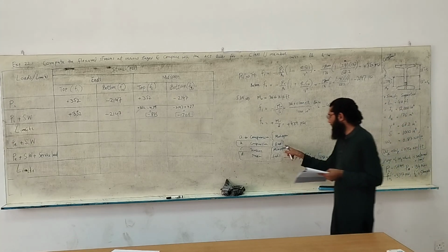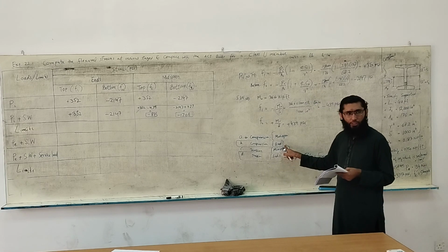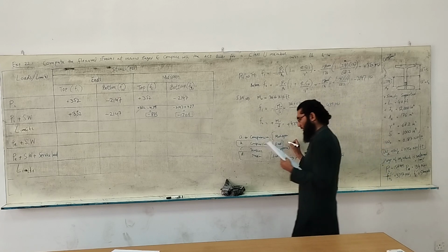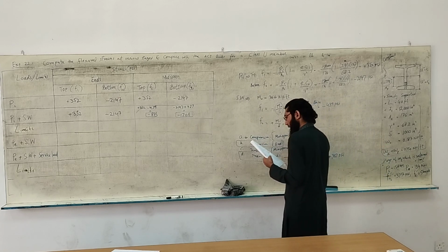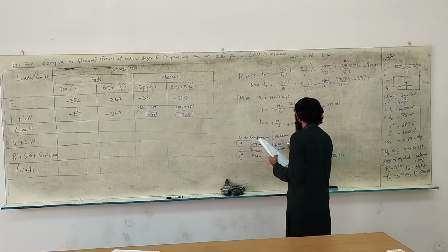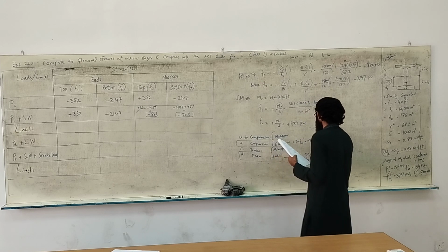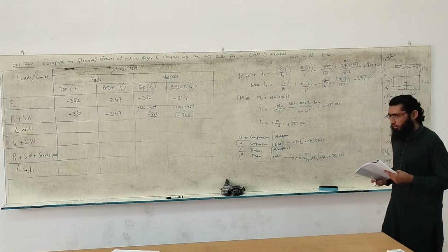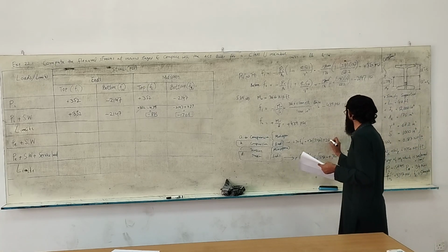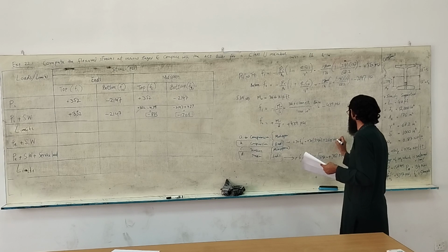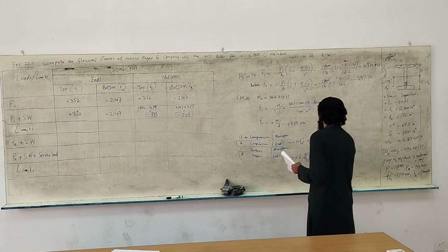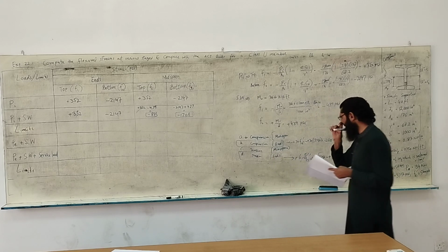Now, for the ends, again, the compression limits given and stated in the code are for uncracked members. We are looking at the limits for uncracked members. It is 0.70 f'ci prime. Now you can just do the calculations. 3750, and what is the answer? 2625. Can anybody else confirm this? Let's put a negative number over here just to reinforce that we're talking about limits for compression.